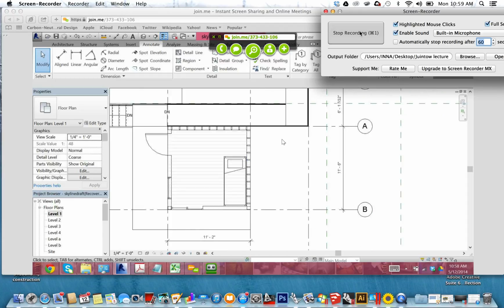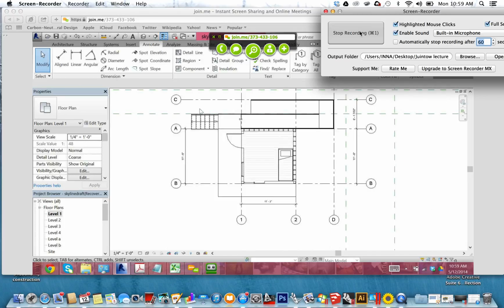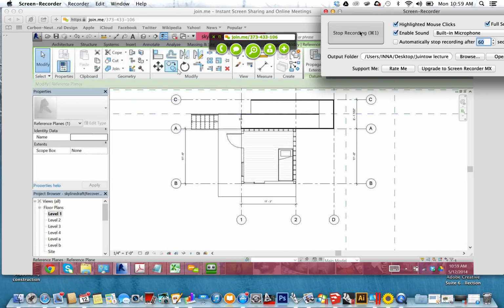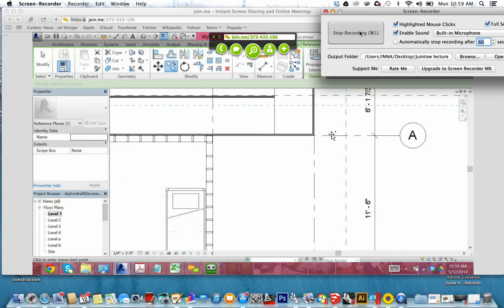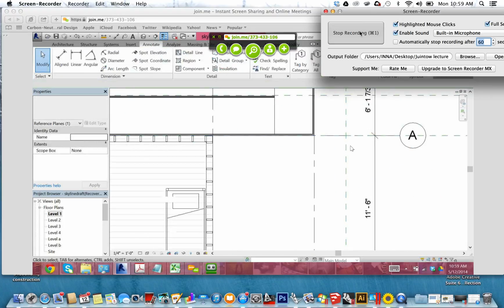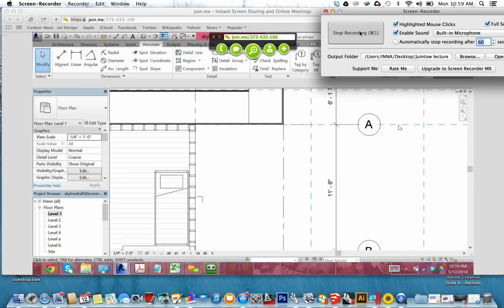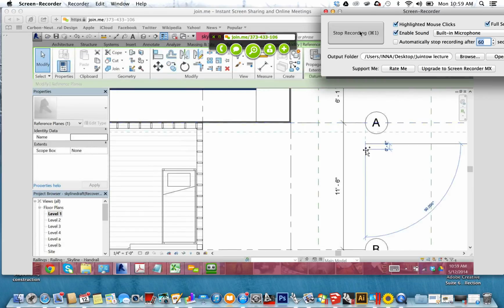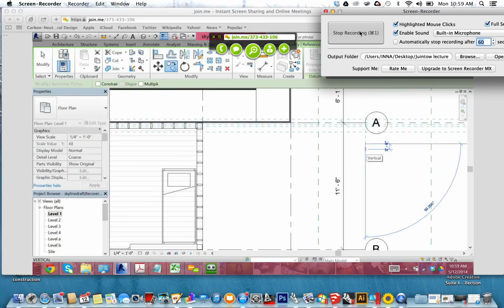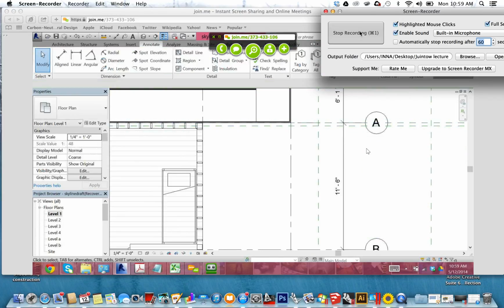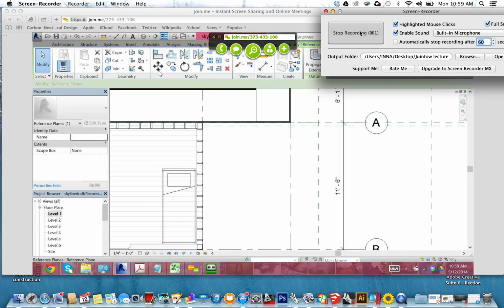So actually, the other thing we should do is size this unit for the joist, for the stud spacing, okay? We don't want to waste any, so if it's 16-inch on center, we're going to use that, okay? So I'm going to run some reference planes, I think, to deal with this. So I'm going to copy this guy here, and bring it here in line with A. And then I'm going to copy that down, let's just call it 3.5 inches. And I'm going to copy this down.